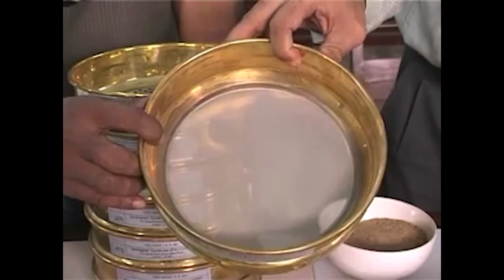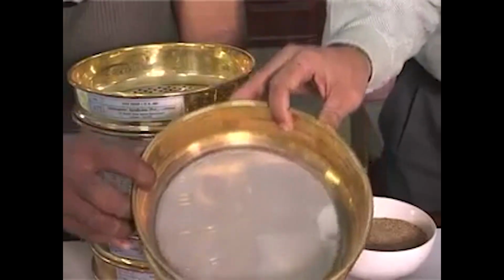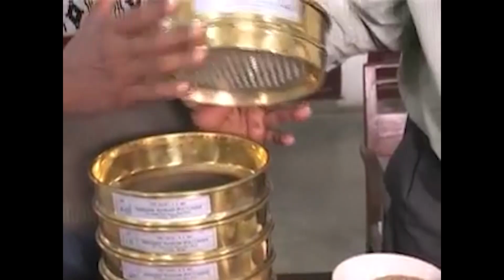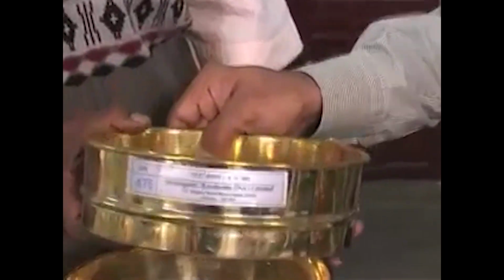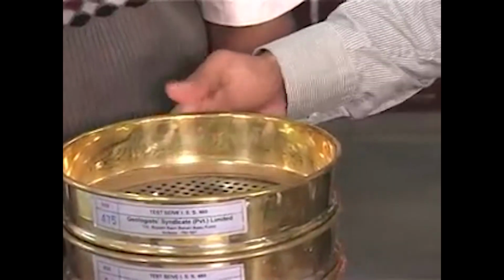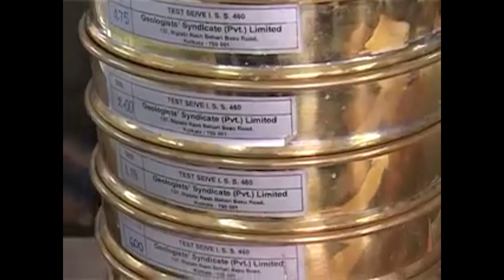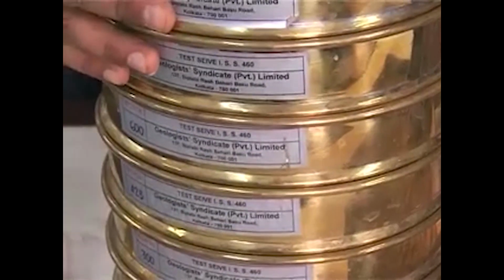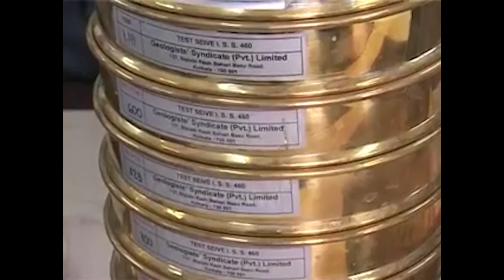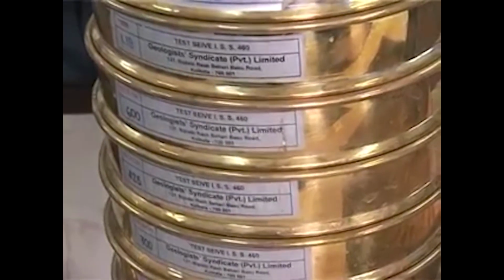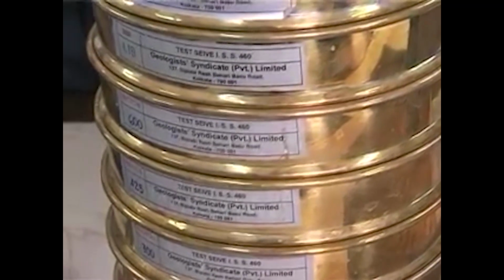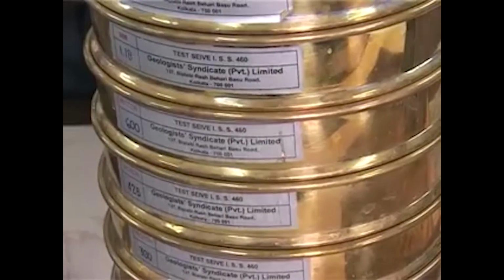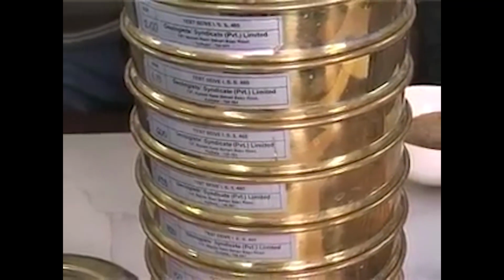This is the 75 micron opening size sieve, whereas the first one that you saw had an opening size of 4.75 millimeter, as is mentioned on the label. And now you can get the idea, and you look at the labels of different standard sieves, and you can see that it actually goes down in size starting from the top, where the coarsest sieve is at the top and the finest sieve size is at the bottom, and at the bottom of the 75 micron sieve is a pan which will collect all those particles which are finer than 75 micron.